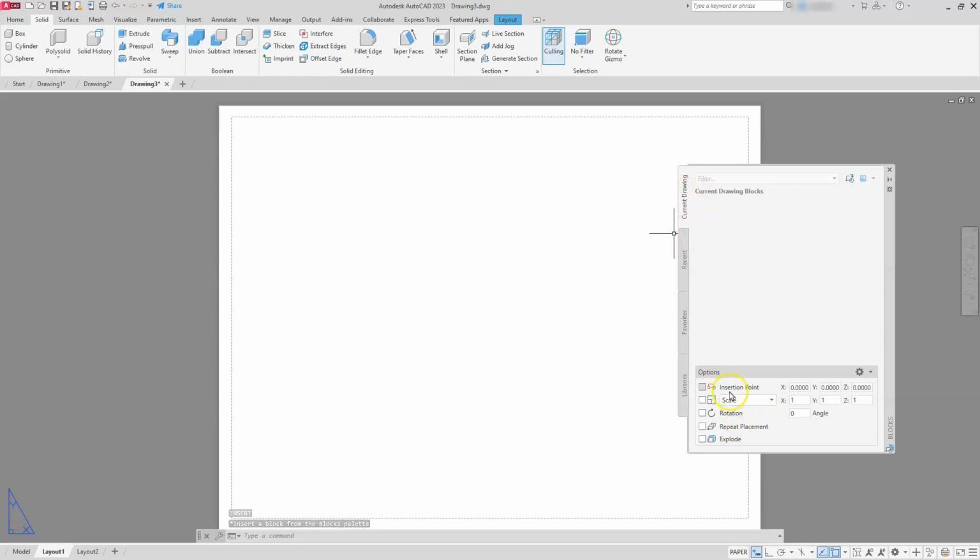Next, I already know the size of this, but remember that we're working in paper space now. So we're going to make sure that we keep the scale set to 1 to 1 to 1 on this one. We're not going to up the size of it. It's not controlled that way. It's going to be controlled by the drawing. And our insertion point, we're going to also keep it 0, 0, 0. So I know that I have both of these two things done already.